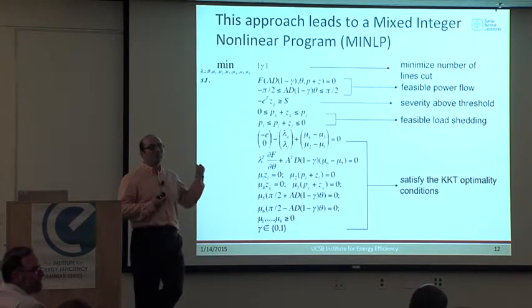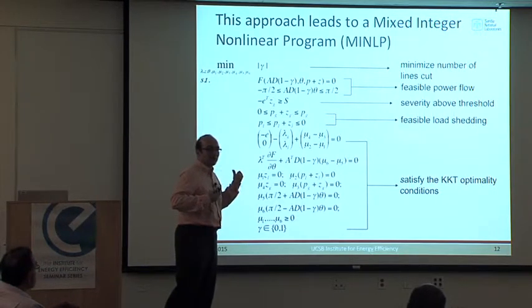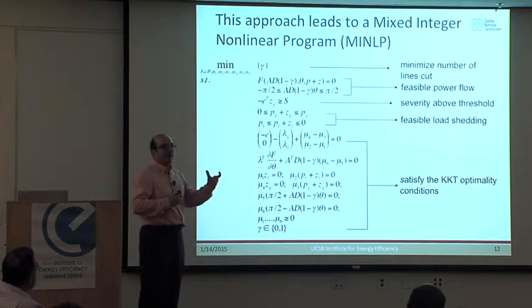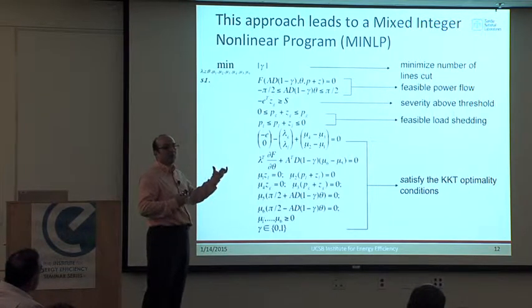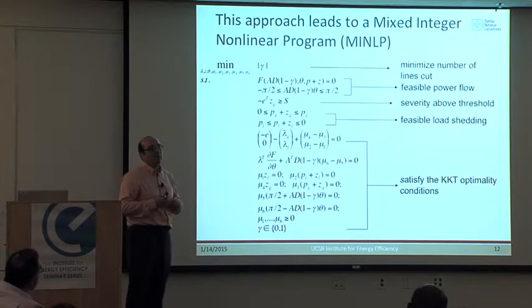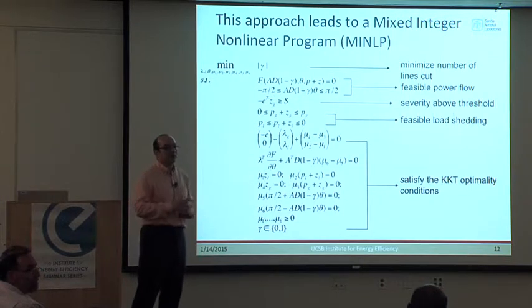So for this formulation, for load shedding, actually, it's already too late. If I lose those lines, the dynamics of cascading will start, and we won't be able to shed the loads. But here, this is an approximation to how big the disturbance will be. In practice, the way load shedding is used is, yes, you want to spread it like peanut butter.